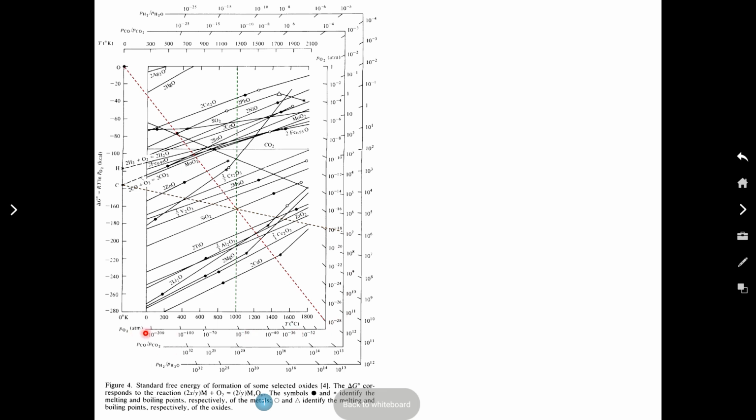But I told you that reaching 10 to the negative 28 atmosphere by diluting oxygen is almost impossible. So if you want to create that kind of pressure, don't even think about diluting oxygen. You immediately say, well, you have to mix CO and CO2 for the equivalent PO2, and you can get that answer from the Ellingham diagram, what that mixing ratio should be.